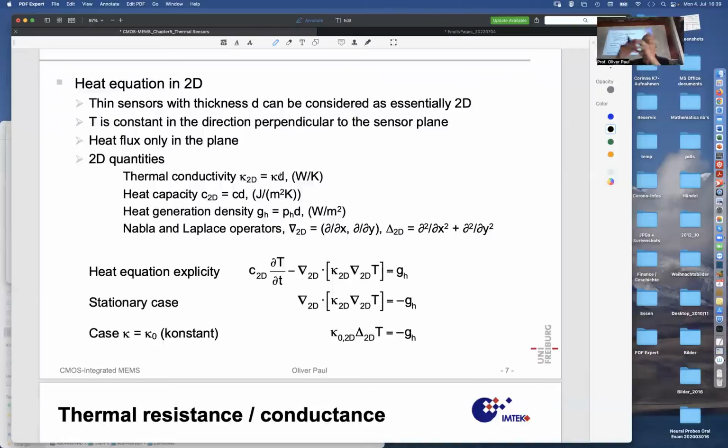d is the thickness. If it's a homogeneous material, we have the thickness of that material, and we have the kappa of that material. So let me draw this now. This conductive thin material, in which the temperature is observed as a function of x and y, and z is inexistent because it's all happening within this thickness d. And this material is supposed to have thermal conductivity kappa, and so the object that plays a role is kappa times d.